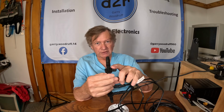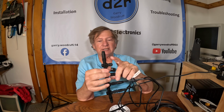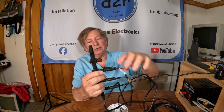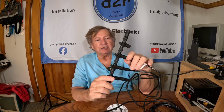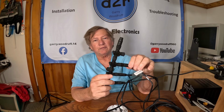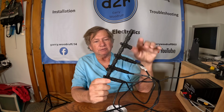I have seen a lot of issues where somebody will connect a device coming on the side here, and they'll put the terminator here, or they'll put 2 power nodes into the network. None of those work, okay? Or if you forget to simply power up your NMEA bus, that doesn't work very well either. It will work for some devices, but not all devices. So just follow the basic rules.